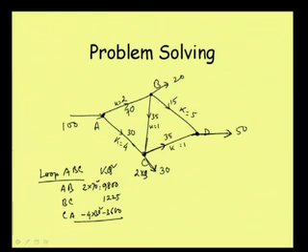Now if we sum up this value, the summation of KQ square is becoming 7425. Then what about twice KQ? This twice KQ is becoming 280 for the first loop, then this is 70. Here we are not considering positive or negative sign, everything is absolute value, 240. So this value is becoming 590. So the summation of twice KQ is becoming 590. Fine.